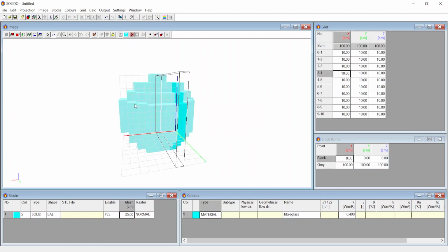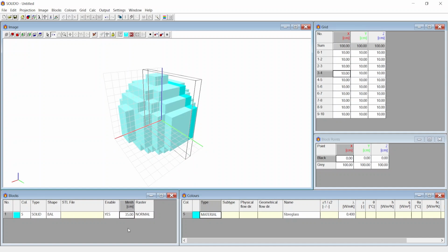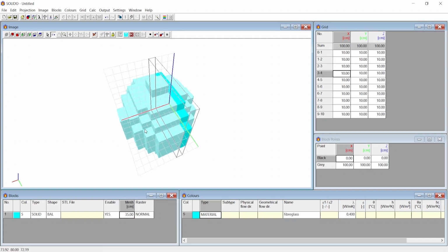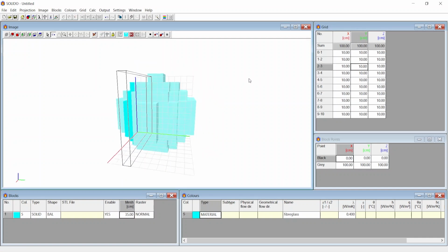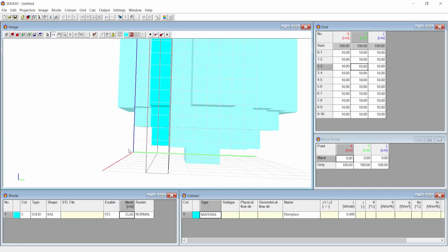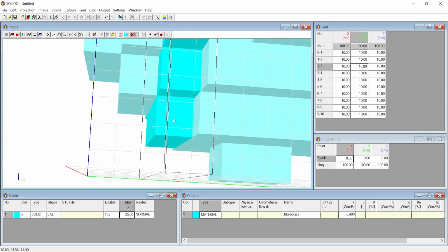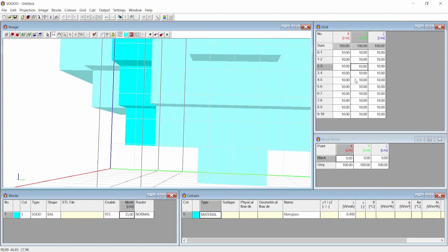Here we need to understand the difference between a grid mesh and a triangulation mesh. The triangulated mesh is generated using the Fill Object tool. Grid mesh, on the other hand, is defined in the grid window to develop a 3D voxel space. This is like a pixeled canvas in 3 dimensions. Rasterize checks if there is a triangulated object at the center of each voxel. If yes, then it fills that entire voxel where it detects material.